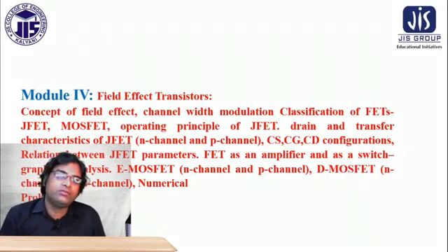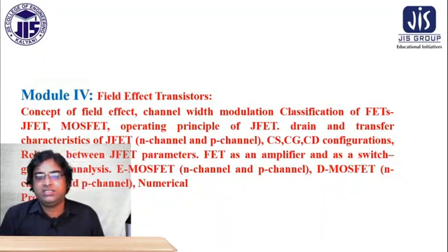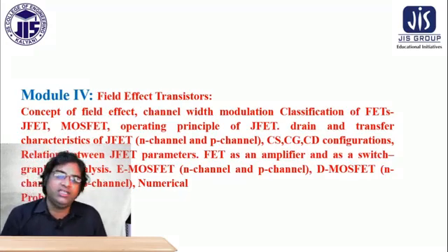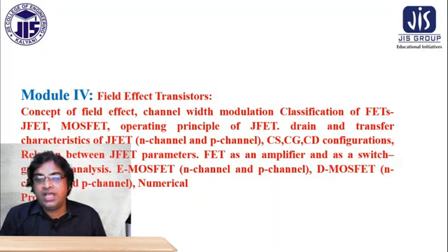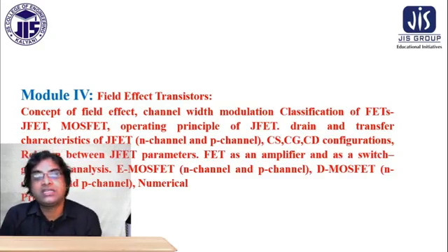Then I go for module 4, that is the field effect transistor. This is somewhat different from the BJT, an advanced version of the BJT, showing how the field effect transistor concept is introduced from the BJT. This is a voltage controlled device, and we can understand how it works, the concept of the field effect, channel width modulation, classifications, FET, JFET and MOSFET, the operating principle of the JFET, and the drain and transfer characteristics, which are very important.